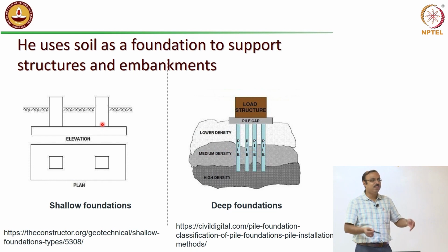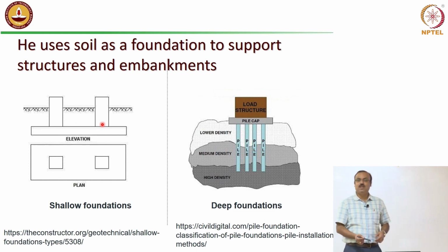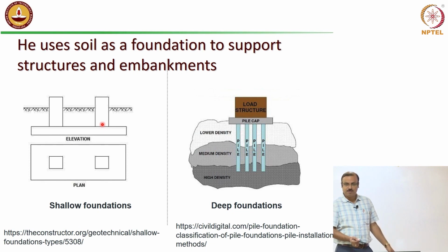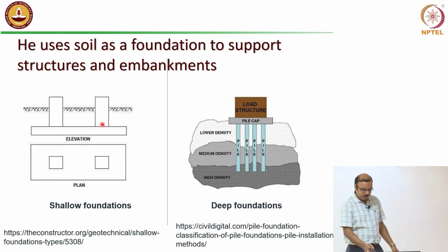So, that is why I am sinking up to a certain level. What you have to do is simply transfer the load to a deeper depth. That is where the term deep foundation comes into the picture. Now, this is a structure, maybe a heavily loaded structure, and then there are piles. These members are like your columns. They will transfer the load to a much better soil which has very high density.